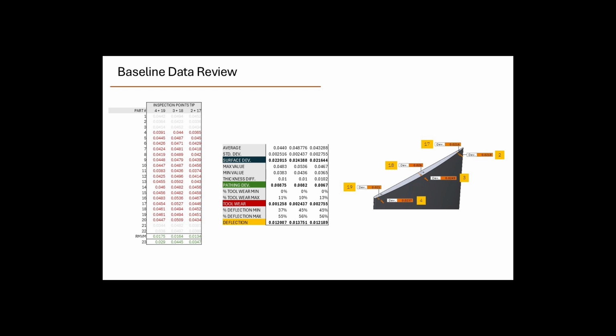But if we add them together, we're effectively getting the thickness across those 2 points at that point on the blade tip. So what we do is we get a surface deviation by halving the total thickness. We're equally distributing the deviation. The reason we're doing that is that, by doing it this way, we're effectively compensating for the distortion of the part, because we've already got that through simulation.